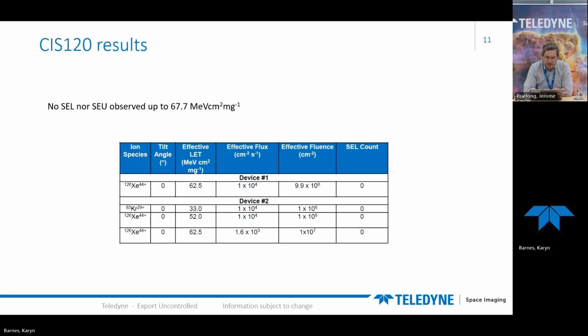And that can be done, for the SEU, via some design approach, as I mentioned, using the modeling from MUSCA to design cells properly to be immune in the first place, but also other approaches like triple modular redundancy. For the latch-up, in order to minimize the gain within the thyristor of the latch-up loop, specific design rules are applied to minimize the possibility of this latch-up.